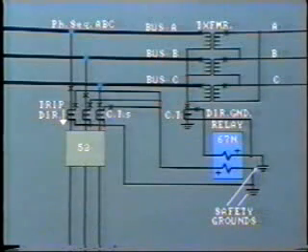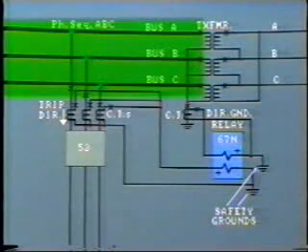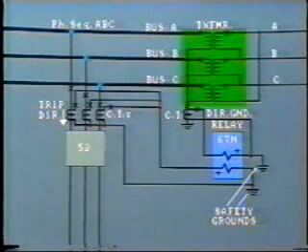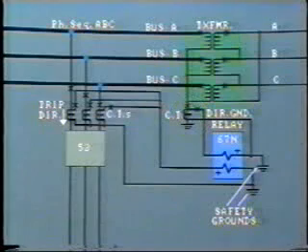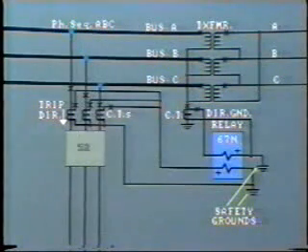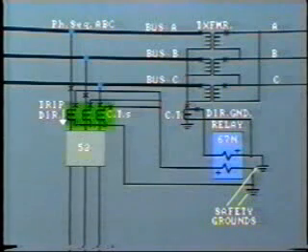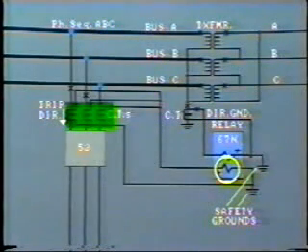Many relays operate by comparing phase relationship between voltage and current, or perhaps some other quantity. A typical example is the directional sensing relay that we discussed in the previous videotape. Here we see typical connections for a directional ground fault relay. This 33 kilovolt bus is being fed from the secondary of the transformer, which is Y connected and has a grounded neutral. The outgoing feeder is protected by this breaker, and the three line CTs are connected to the sensing coil of the directional relay.